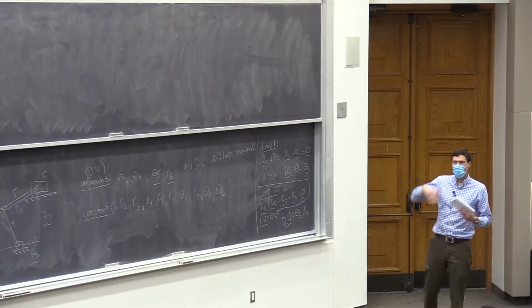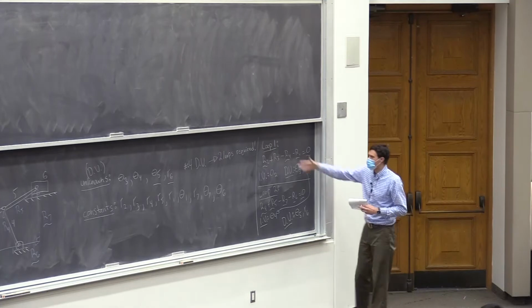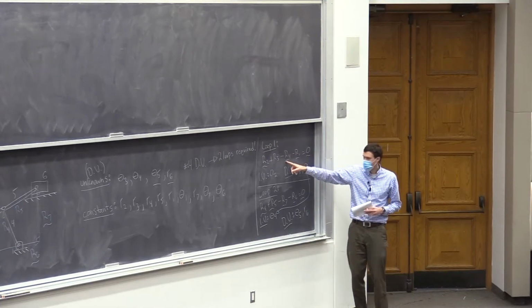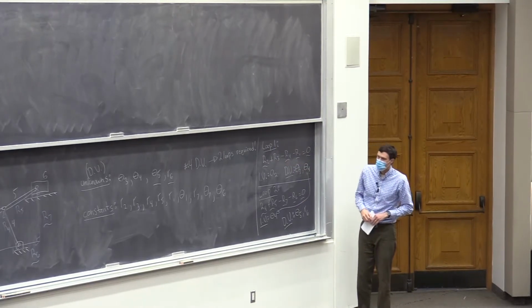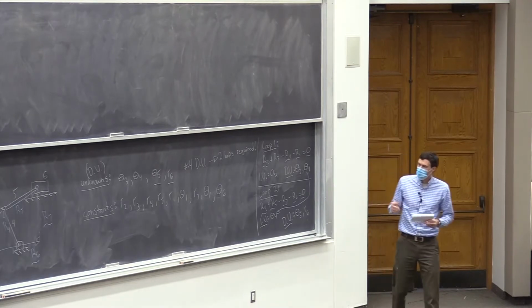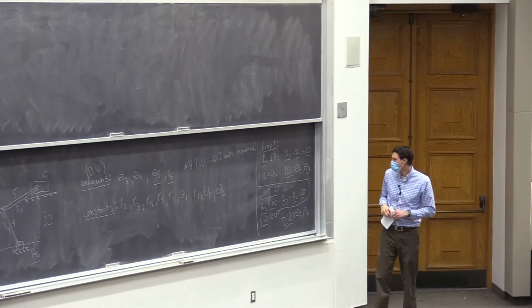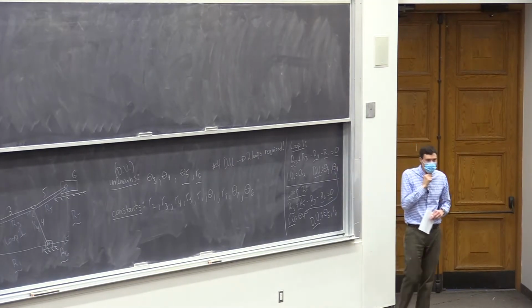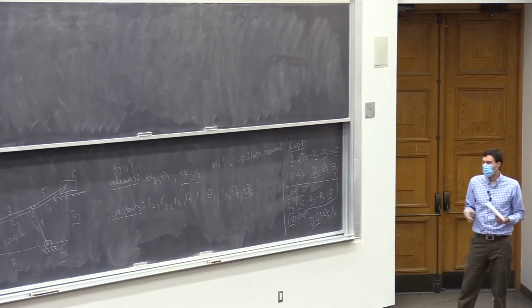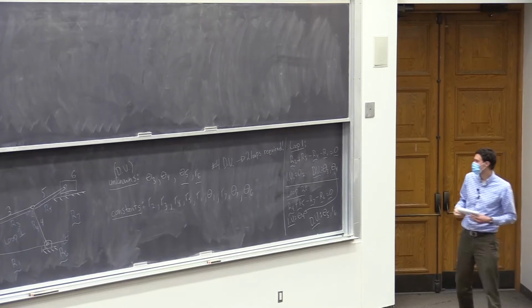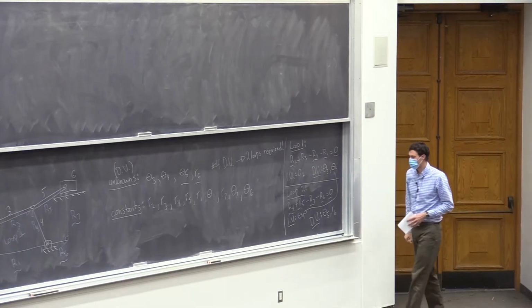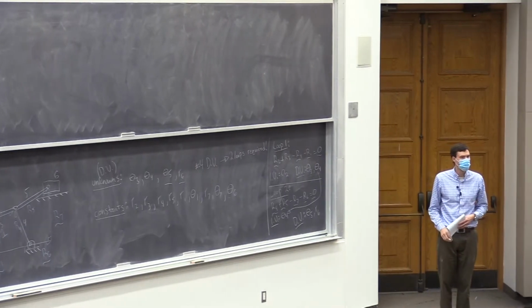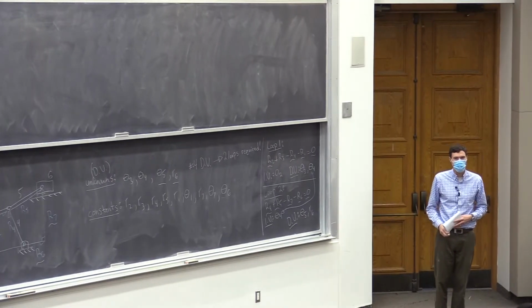The most complex problems, this one is not too bad, because loop 1 can be solved on its own, and then plug that into loop 2. You could have a really complex mechanism, theoretically, where you'd have to solve all 4 equations simultaneously, although that's not very common in actual mechanisms. So usually you'll be able to solve the first one and plug it into the second one. Any questions about using 2 loops for this problem?